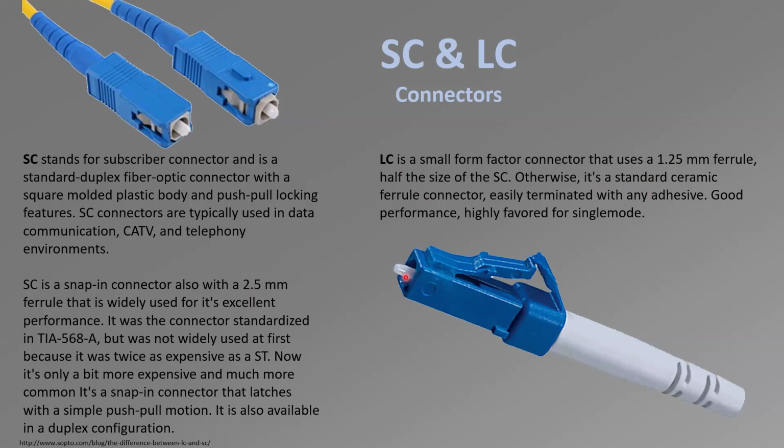Ceramic ferrule is ceramic, which means it can attract static electricity, which means it can attract dust. So you gotta be really careful not to leave that thing uncovered. There's a cap. You should always have it capped. All those ferrules should be capped when not used. Good performance, highly favored for single mode or multi-mode as well.